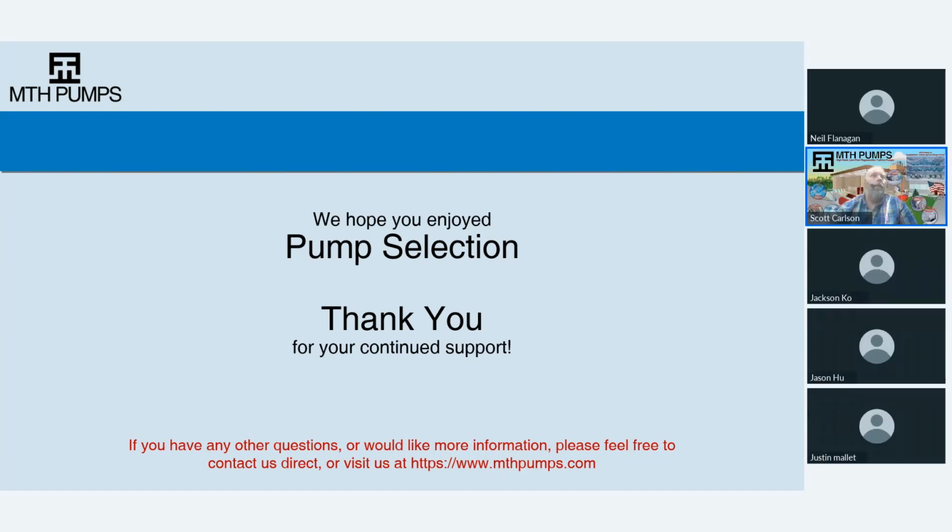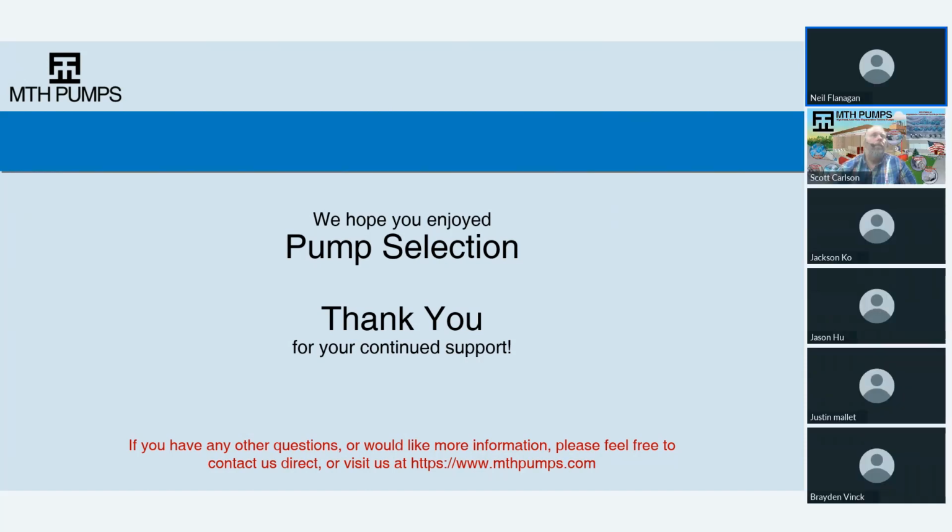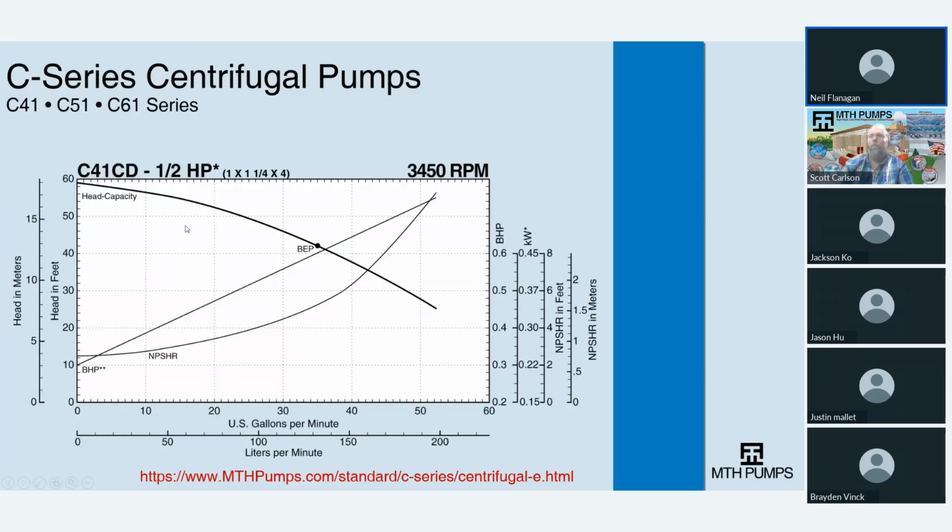Scott, just a quick question on the C-Series. There's no published minimum flow on those, right? Like you can't run them dead, right? Oh, if you did deadhead them, because of the open face design, you would not hurt them, and they will maintain the horsepower without hurting it. It just won't flow.